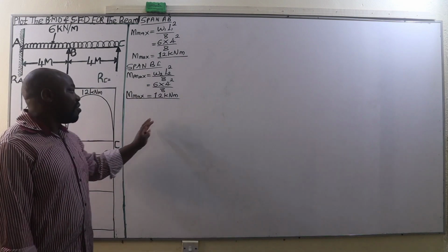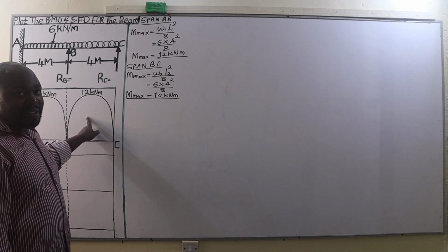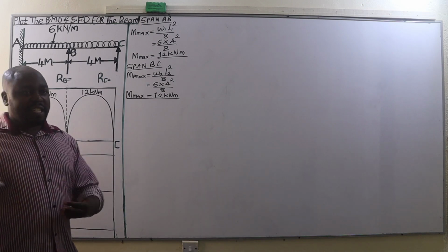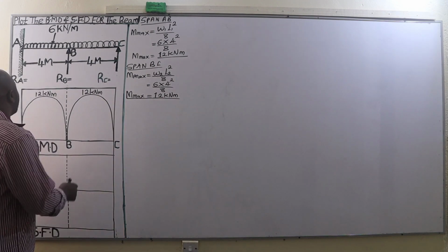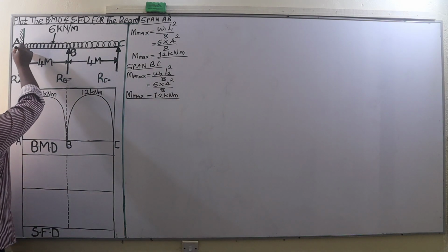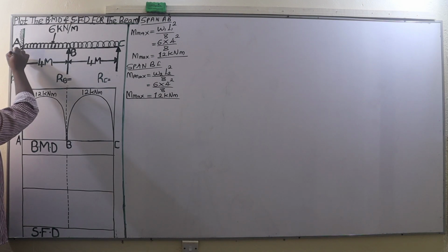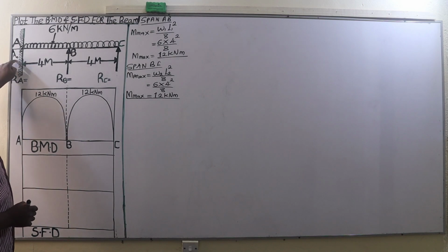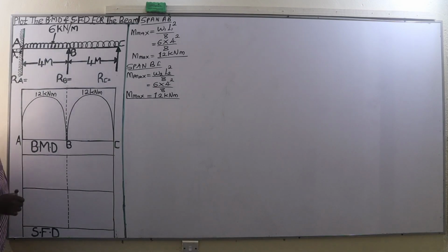Good. Then from there, we are going to calculate the area of each of these bending moment diagrams, as well as the distance of their centers of gravity from A and C respectively. Therefore, we are going to extend an imaginary zero span, like this, and we are going to call this end a support, A naught, and the distance from A naught to A is going to be L naught. So we have L naught there.